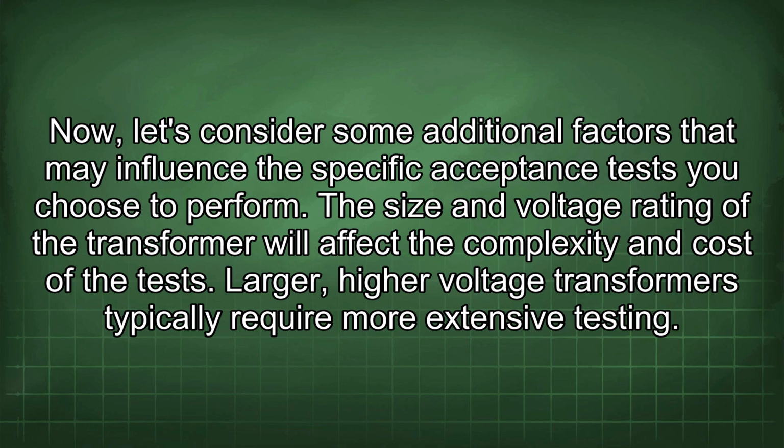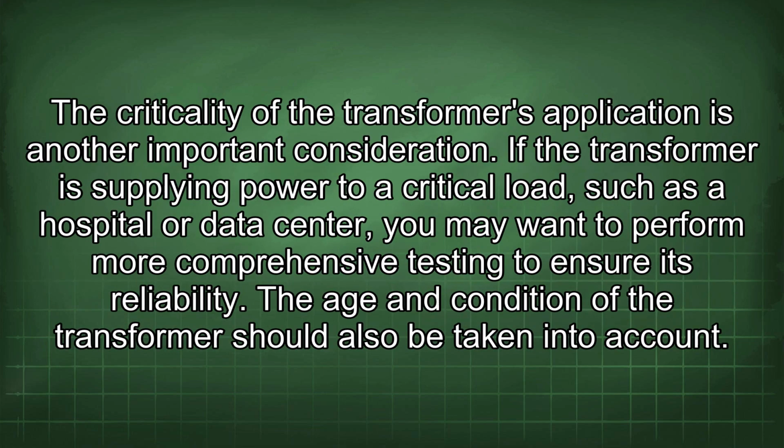Now, let's consider some additional factors that may influence the specific acceptance test you choose to perform. The size and voltage rating of the transformer will affect the complexity and cost of the tests. Larger, higher voltage transformers typically require more extensive testing. The criticality of the transformer's application is another important consideration. If the transformer is supplying power to a critical load, such as a hospital or data center, you may want to perform more comprehensive testing to ensure its reliability.